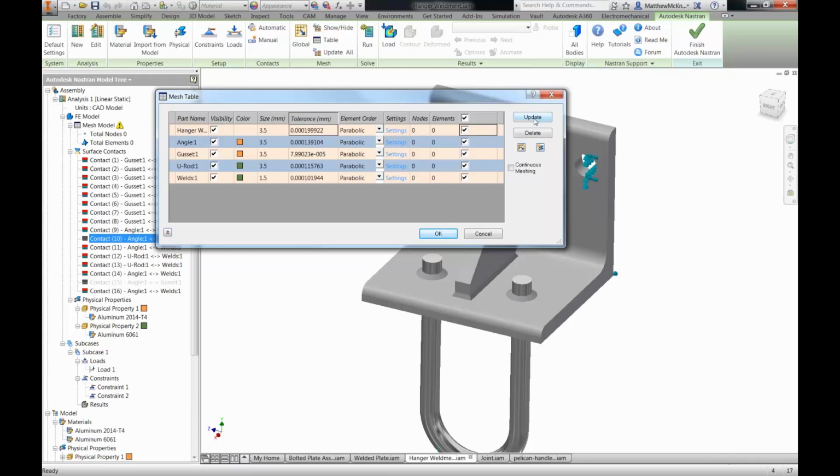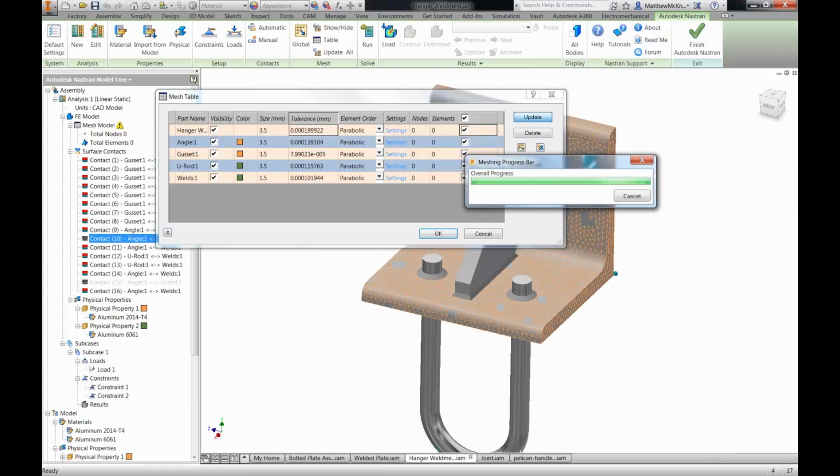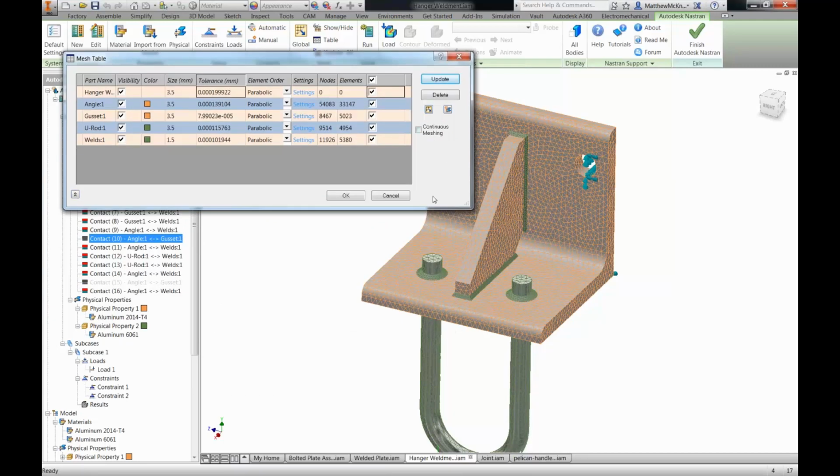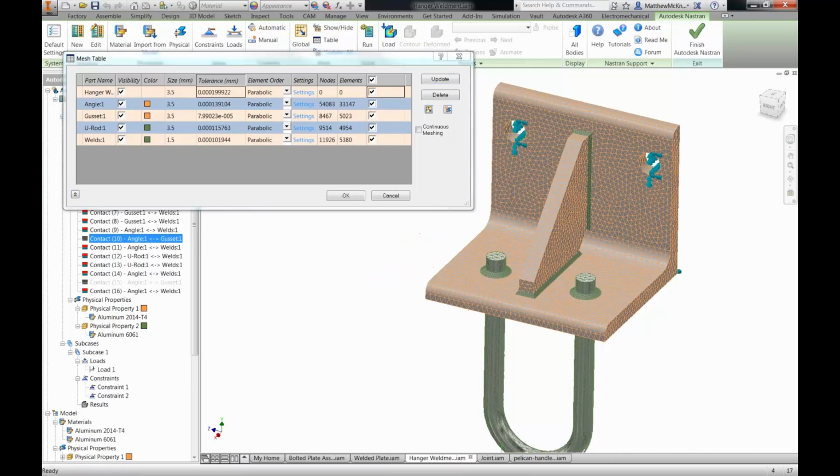And if I then select all of the elements or components and hit update, you'll see that it meshes those in the background for us. So we can use this as a diagnostic tool. If we're having problems with parts that aren't meshing, then we can quite quickly come in here, isolate the ones that are or aren't causing us problems, and then go in and modify those in isolation from the other ones, making it a very efficient method of using this mesh generation tool.